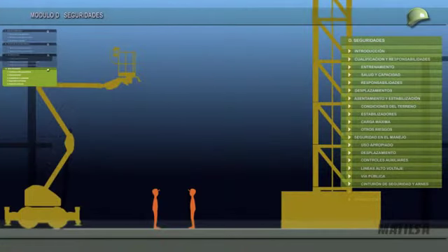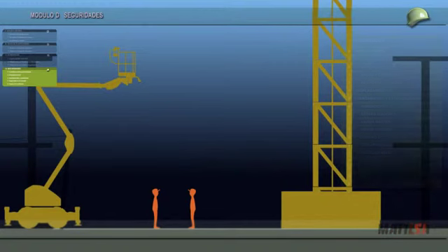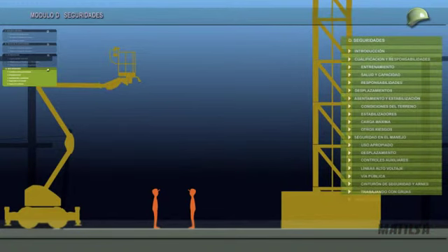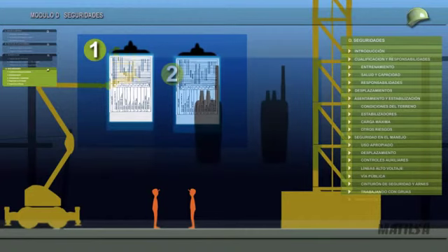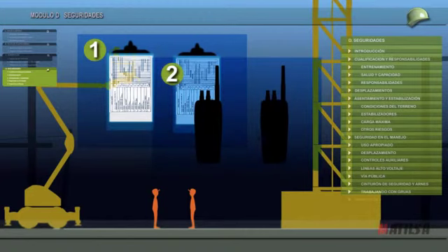Handling of the platforms together with cranes. When an access platform is working with a crane, you should make a daily work plan so that everyone knows the work system that you are going to carry out. Operators of this type of machinery in the same working area should be in continuous communication through radio or walkie-talkies.